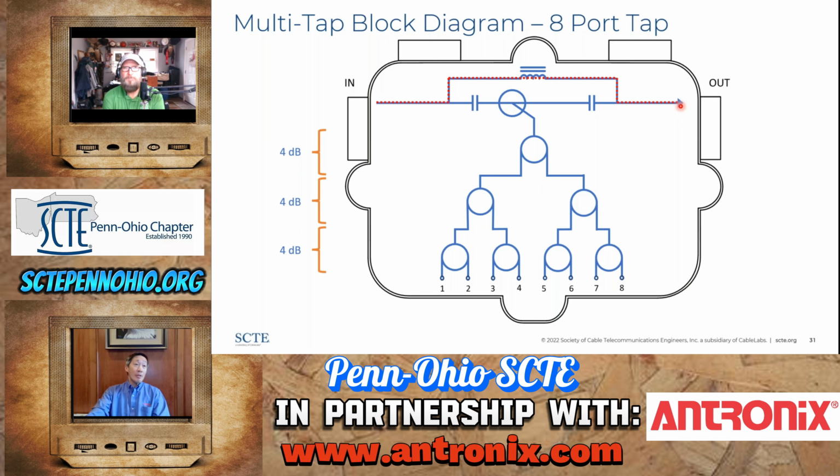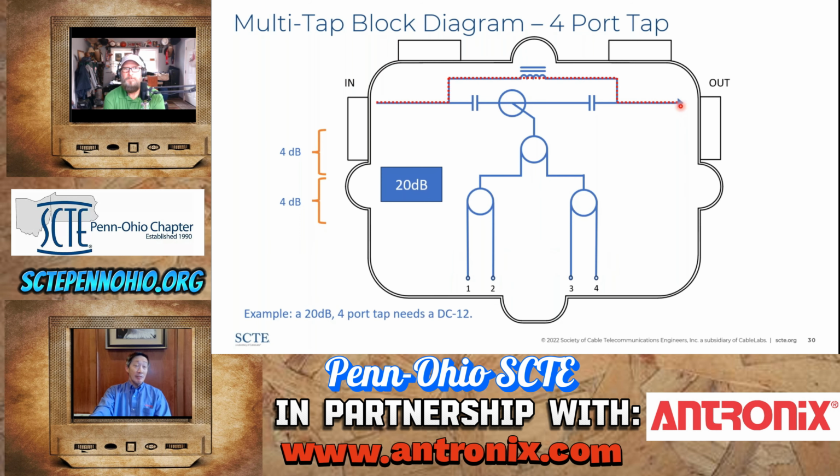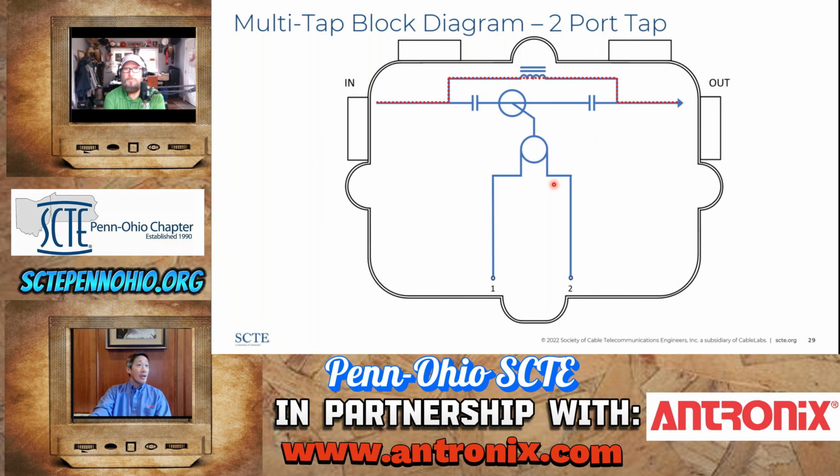But even going from a 2-port to a 4-port tap in the same dB value, we'll have slightly different insertion losses as well, because a 4-port tap has 2 sets of splitters here, and a 2-port tap has 1 set of splitters here. So this directional coupler value is different in the same 20 dB tap on a 2-port tap versus a 4-port tap. So make sure you check the print and use the correct value tap that you need for your design.